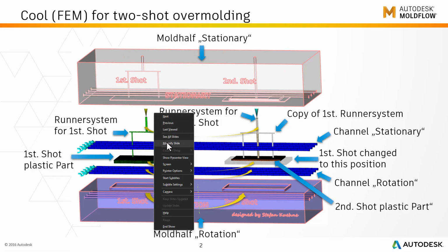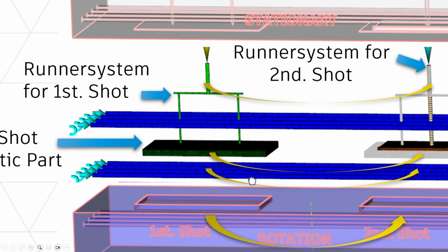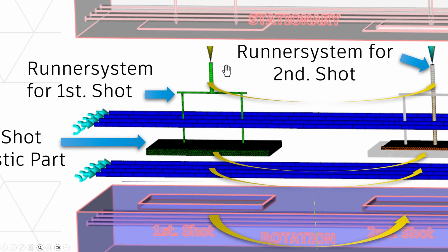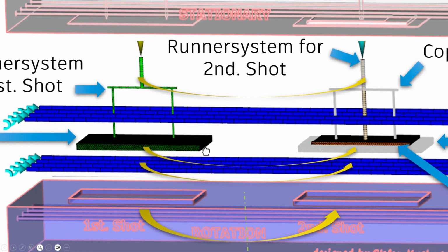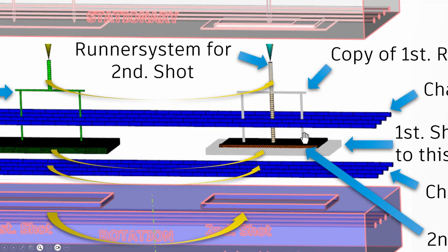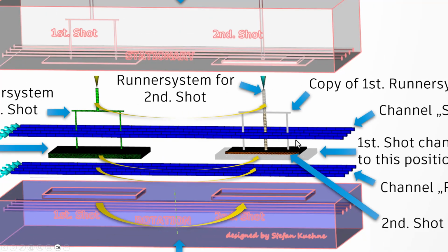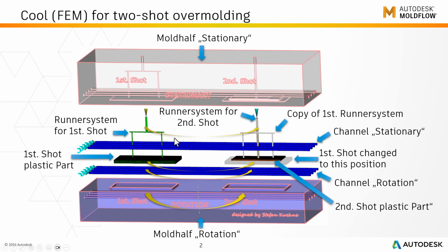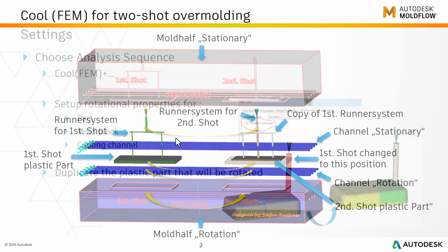But if you go a little bit in, let me magnify and show it to you. So this is actually going to be a first shot model, and then you have to model the second shot as well. Of course, in both cases, you have to model the first shot and the second shot, and then you rotate it. Maybe you have to model a center line over here and then rotate it, and then you can also model the cooling channels as you model in the actual mold. In fact, I would say that you can model the complete core and cavity, and you can see in detail how it has been done.